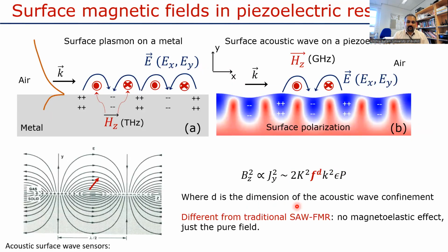But this requires us to engineer magnetic fields. And this is the main insight that we had in this work: traditionally, piezoelectric devices are solved in the so-called quasi-static regime. So basically you assume that you force the magnetic field to be zero. On the other hand, this is not really true, because ultimately you have to solve Maxwell's equations, and the quasi-static approximation is an approximation. Once you go into the gigahertz frequency domain, this is not true.